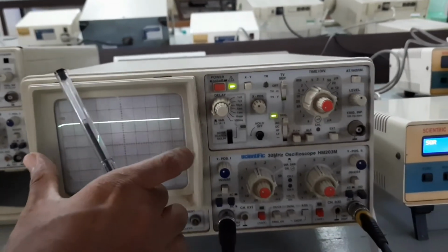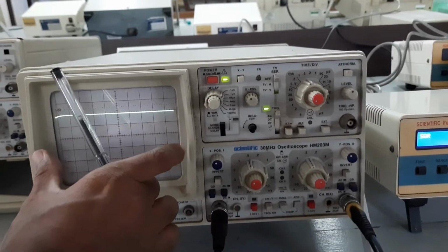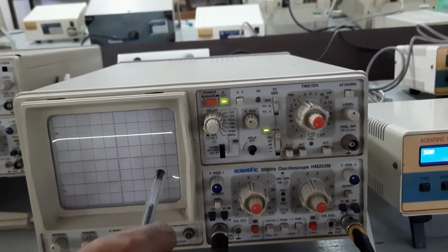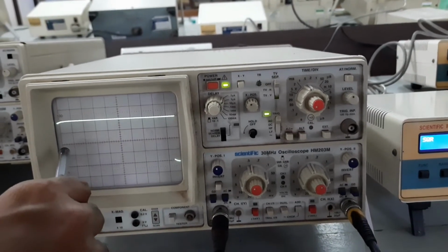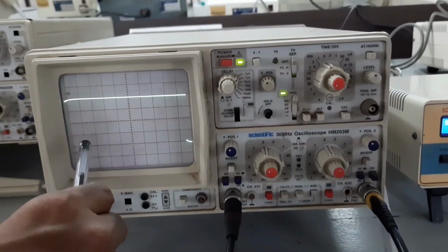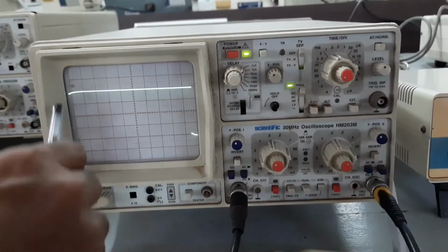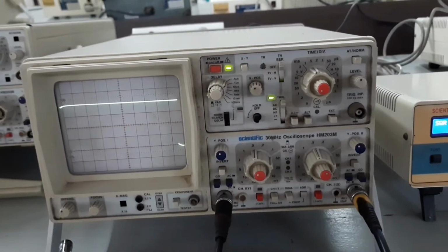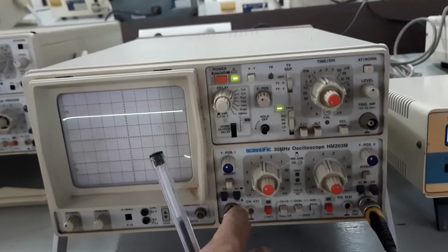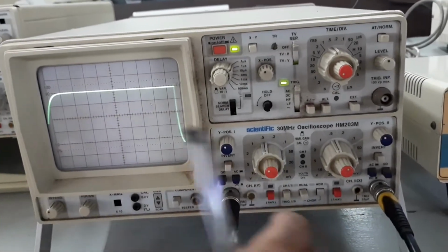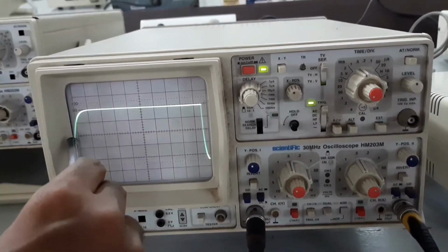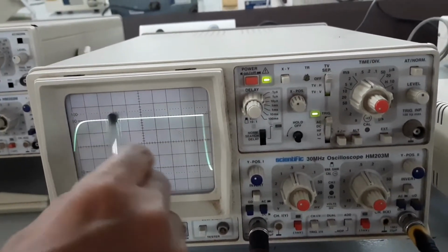If you observe this particular duration, this is much larger compared to the time constant of the circuit. So for this particular circuit, this will appear as a step signal because the time constant is only 0.1 millisecond, and this is much larger than 0.1 millisecond for this particular time per division. So this is acting as a step signal, and you can observe the output here. The output I have connected to the other channel. So the first order response, that is the exponential rise of the output, you can observe here.